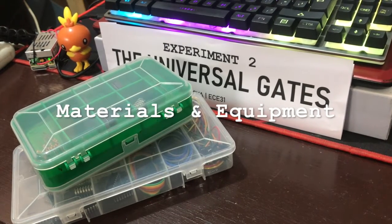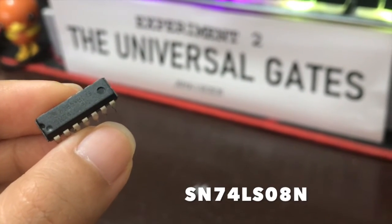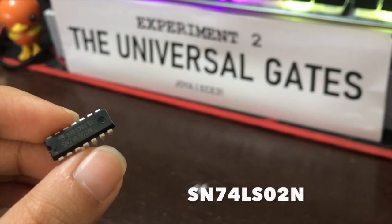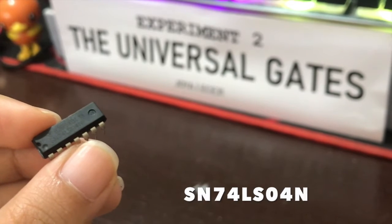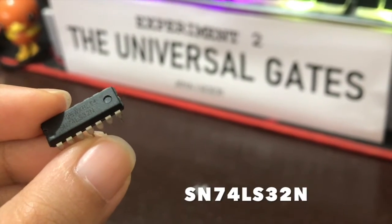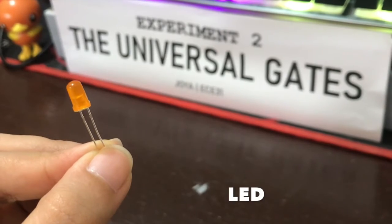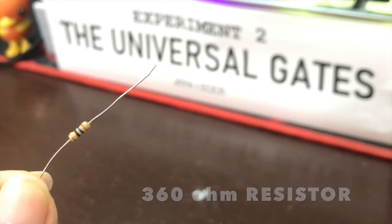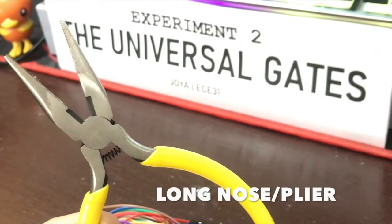The materials and equipment needed for this experiment: one 7408 AND gate, a 7400 NAND gate, a 7402 NOR gate, a 7404 hex inverter gate, a 7408 AND gate, a 7432 OR gate, a power supply with a 5-volt output, an LED, a resistor with a 360 ohm resistance, a breadboard, connecting wires, and a long nose pliers.